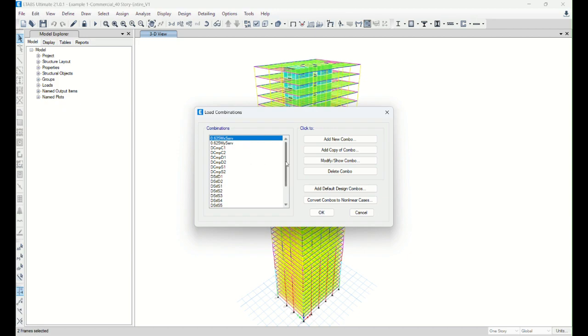But for deflections, again, building deflection is similar to beam deflection. We're using live load deflection, where we try to limit it to less than L over 360, or for total deflection we're using a limit of L over 240, something like that. It's all based upon service load, which has no load factor on it.